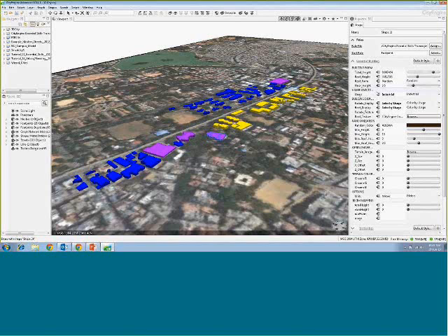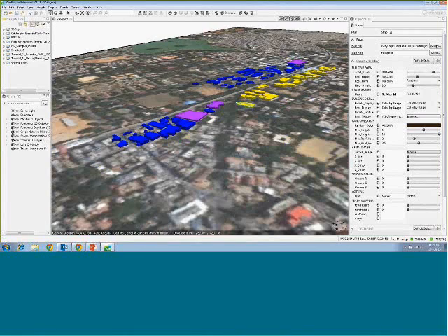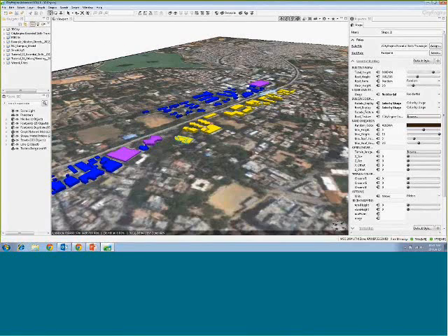So as you see, the planners in the process of geodesign can not only thematically visualize their data in 3D, but they could also create a facade based or more textured approach. If we want to create the same textured approach over these particular model buildings, what I could do is apply textures or apply rules on my model buildings. This creates a complete 3D view of my buildings, and I could model my buildings using simple rules.